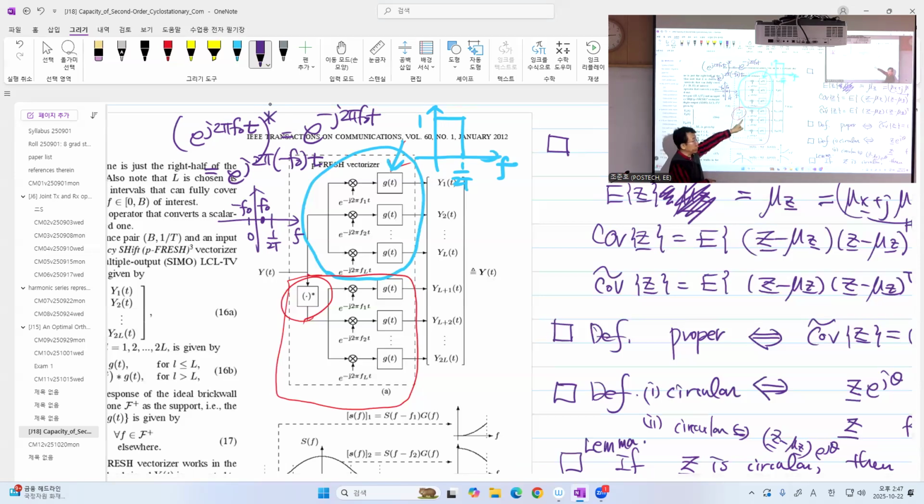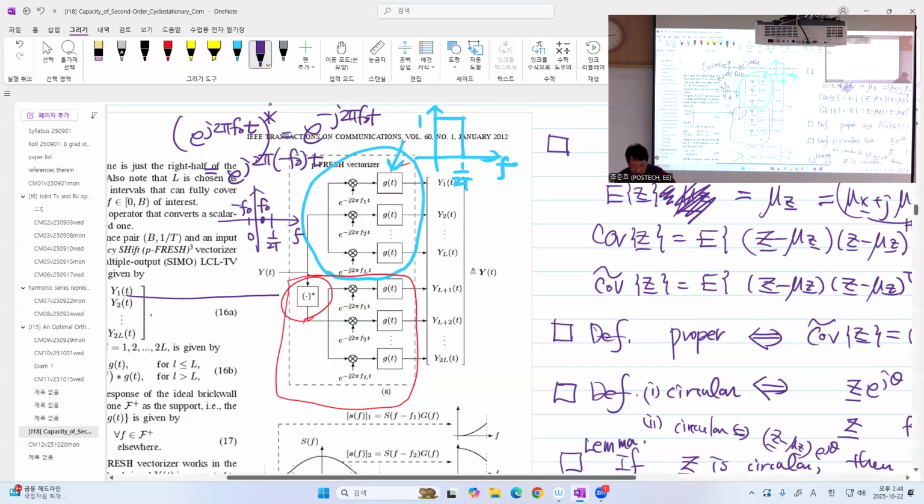And unfortunately, after any shift, this strange positive-part filtering will not pass you. You are blocked. So what happens? This frequency component only appears in one of the upper part, one branch of the upper part only. Got it? So in the same way, you now may consider dividing the entire frequency band into subintervals of length 1 over T.